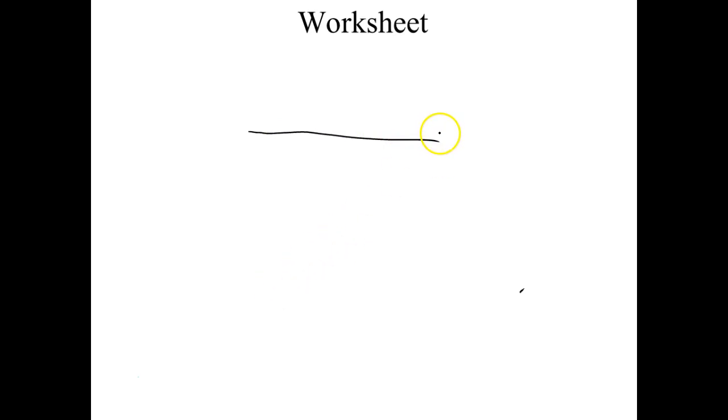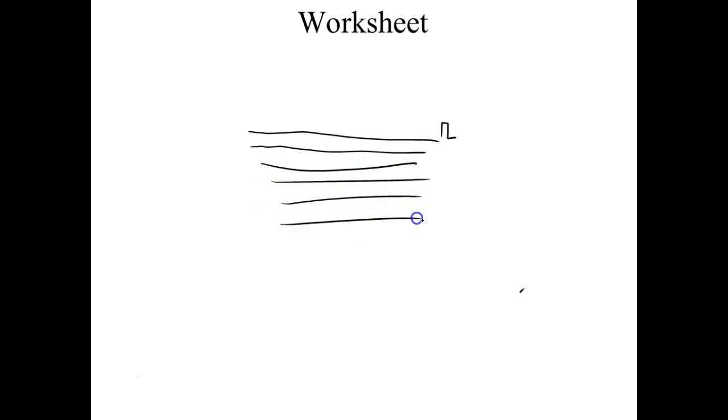And then when we get over to this side, what do we want to do? We want to tell our receiver that we've finished transmitting a line. And then it would drop down to another one and another one and another one. At the end of each one of these, we need to synchronize to tell our receiver when to reset back over to the left.